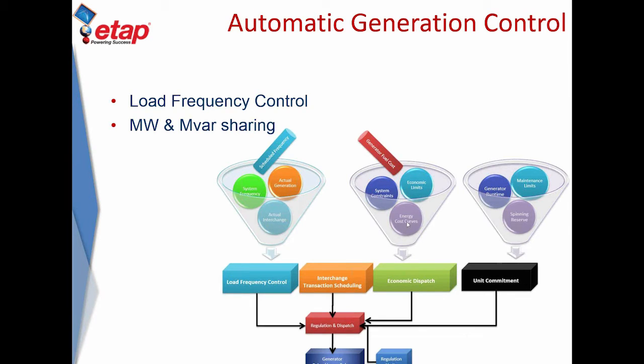The economic dispatch essentially looks at the conventional generation fuel cost and economic constraints, and it looks at the energy cost curves from the power grid. Therefore, it's essentially looking at the tariff or the rate at which you're buying and selling power and the rate at which you're burning fuel to generate energy. And then it decides which is the most optimal generation source and which source is closest to the load such that the losses are also minimized. So again, it's a multi-objective solution.